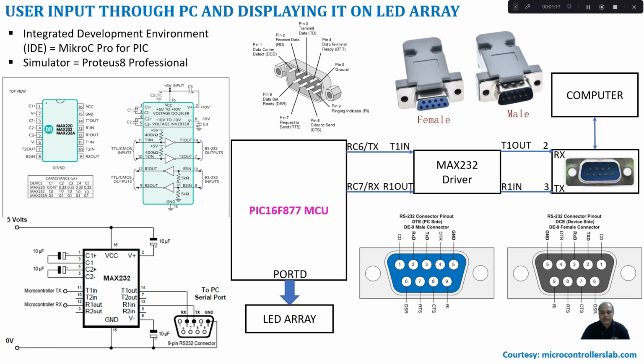A logic 1 is represented by 5 volt, logic 0 is represented by 0 volt. Whereas in a computer, a logic 1 is represented by minus 12 volt and logic 0 by plus 12 volt. So we need both voltage doubling and inversion of the voltage. That is why we make use of a MAX232 driver.